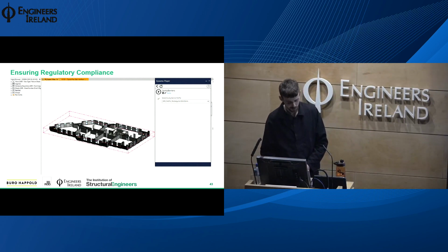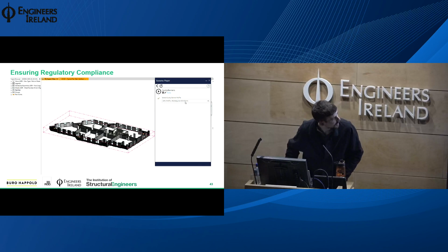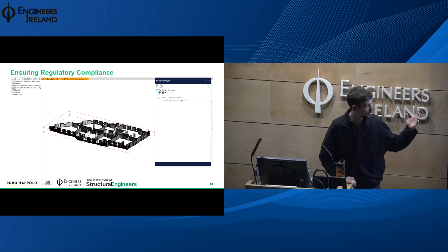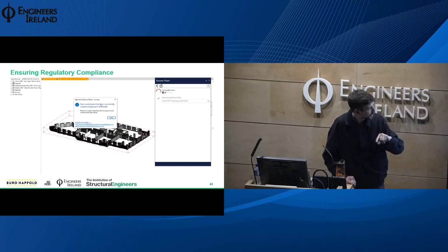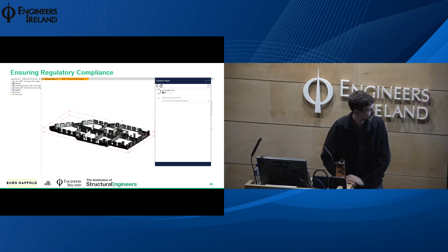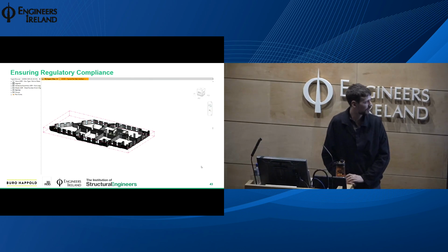The way that this works is that you select a profile for your cavity barrier, you hit play on the script, select the slab that exists in the structural engineer's model, and that then just rips the geometry from that slab into our scripting space, sweeps the profile of that cavity barrier around the space, and tells you that it's been successfully modelled.